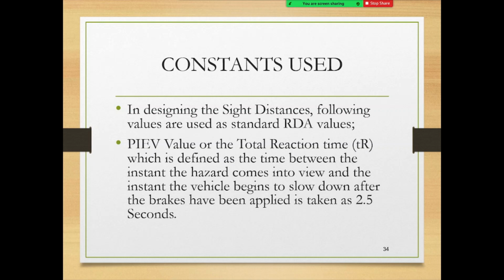Through research, people have understood that for that activity, it takes 2.5 seconds. Processing, that means reaching that visual information to your eye and up to the pressing of the brake, takes 2.5 seconds for an average healthy man who is not under liquor, right?